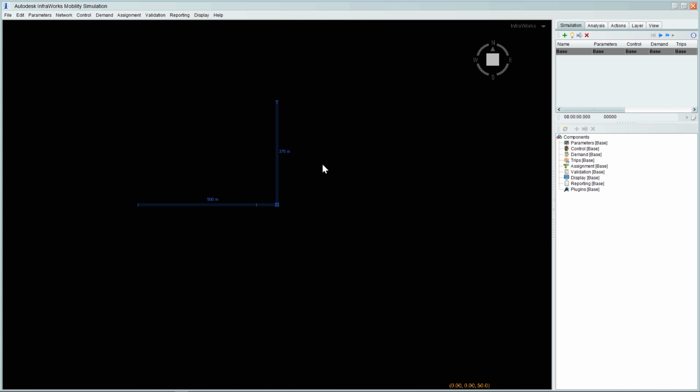Okay, so let's make a start on this then. Housekeeping first, we've just gone into a brand new model, and as in the previous session, there's a few things that we need to do. So number one, we're not in orthographic mode, so there's nothing displayed here, so it's in perspective mode. So to get it into orthographic, I just type O on the keyboard, and you can see it's now in orthographic mode,